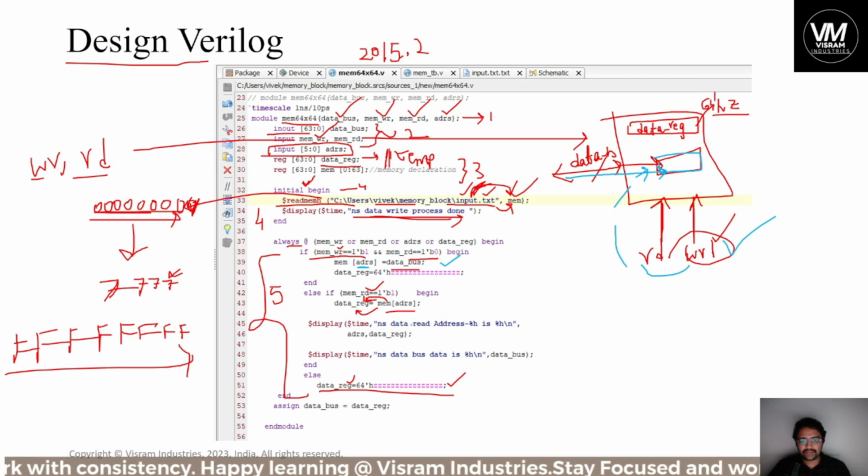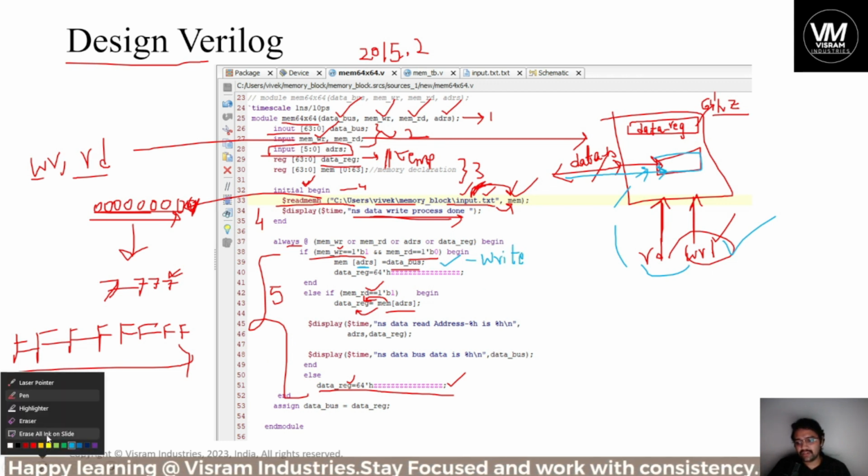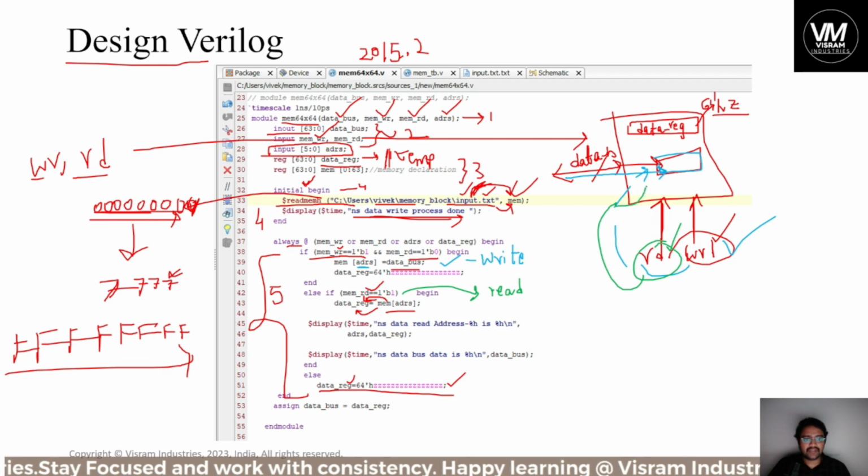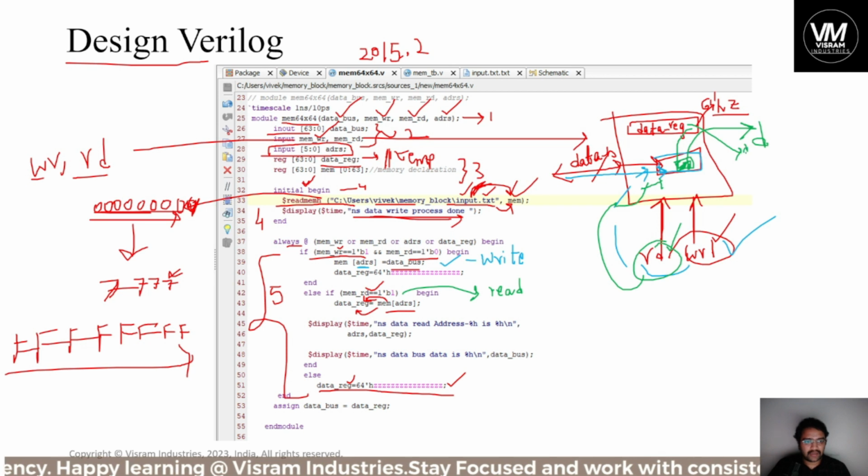Okay, so after that, else if it is the write condition. Now let us talk about the read condition. So else begin, it is the read condition. In the read condition, read is enabled, hence read is nothing but whatever data you have, that piece of data should be sent through data out, I mean via the data register and data register to data out.